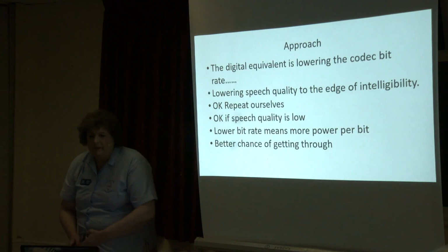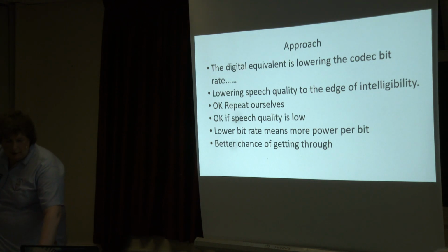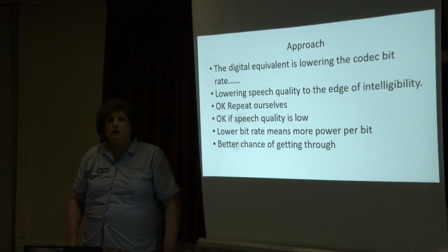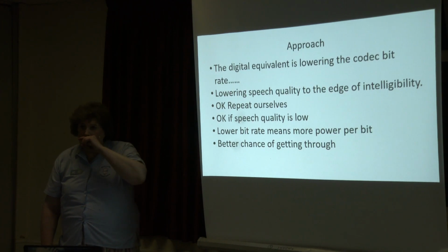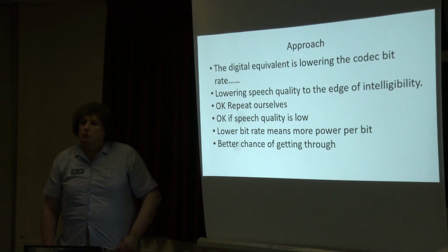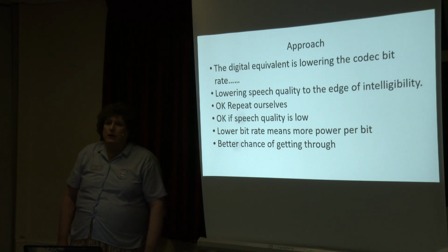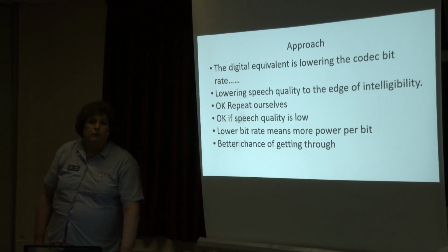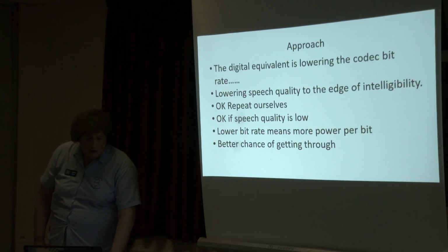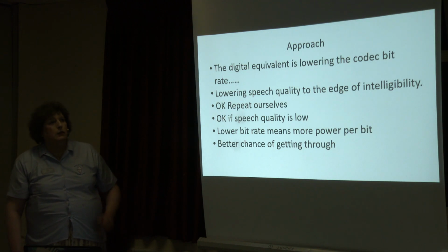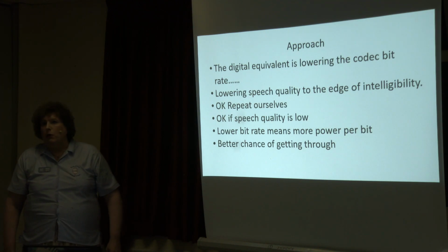Right, now, first of all, one of the biggest mistakes a lot of people make when they use digital is they put the modulation into the transmitter and they wind it right up to full power. With digital modes you only need approximately 25 to 33% of the normal audio. So if you've got a 100 watt transmitter, then really you should not be exceeding 30 watts when you're using digital modes.